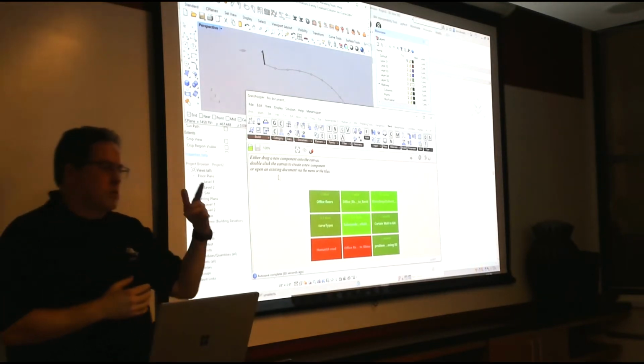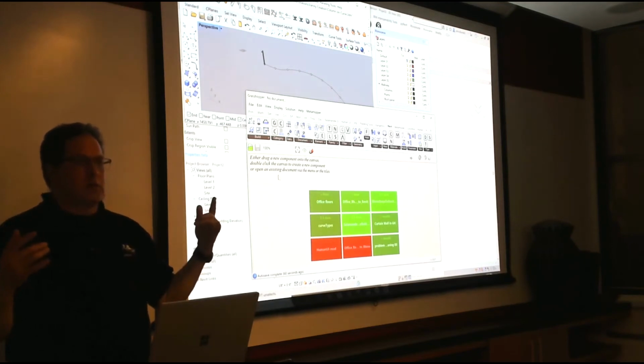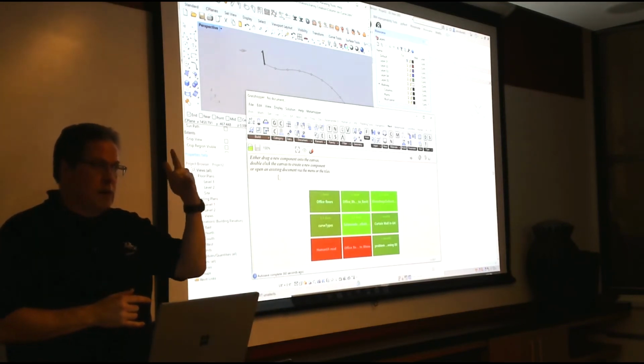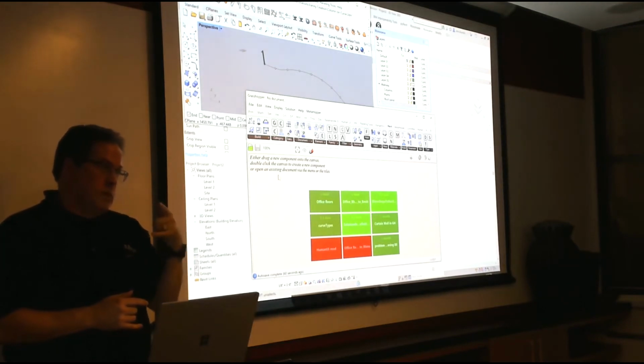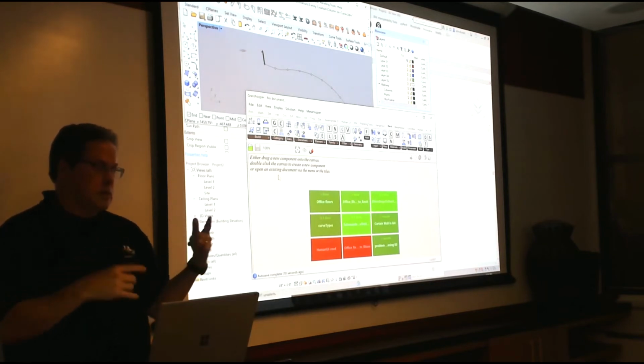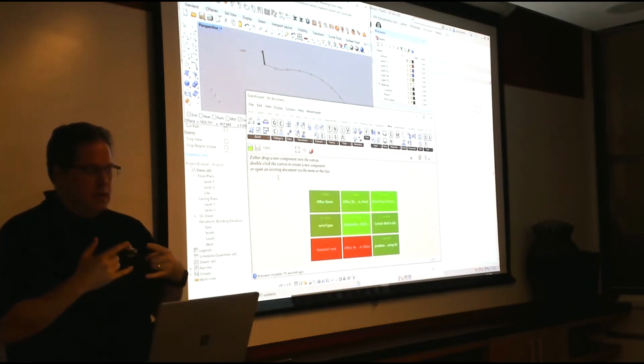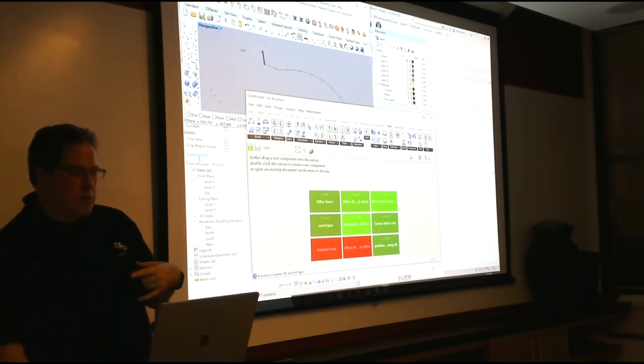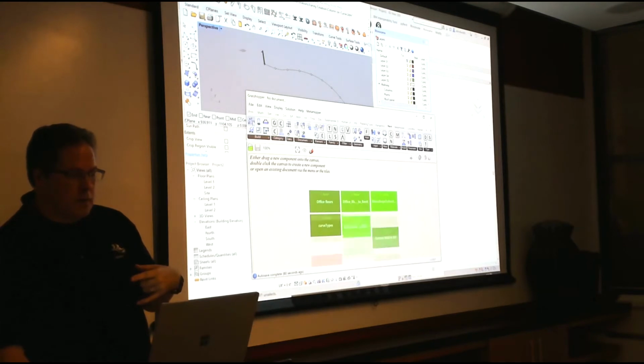So curtain walls, we should talk about curtain walls in general. Facades in general, right? So facades, we always play the same game in Revit. We have the standard everyday curtain wall, which you can drive through Grasshopper if you really want to, right? Number of divisions, all that kind of stuff. Now, a lot of times our facades are a little more complicated than that, so we want to go to adaptive components. The nice part about adaptive components is we can drive them through Grasshopper, right?